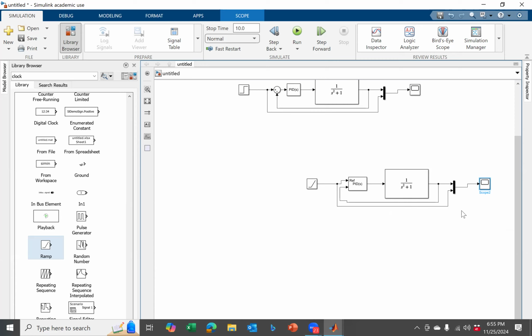The differential equation is theta double dot plus sine theta is equal to u of t. Do you agree with me? So here is what I'm going to do. I'm going to write this equation as theta double dot is equal to minus sine theta plus u of t. Do you agree with me? Now I'm going to code this expression inside Simulink. How do I code this expression inside Simulink?